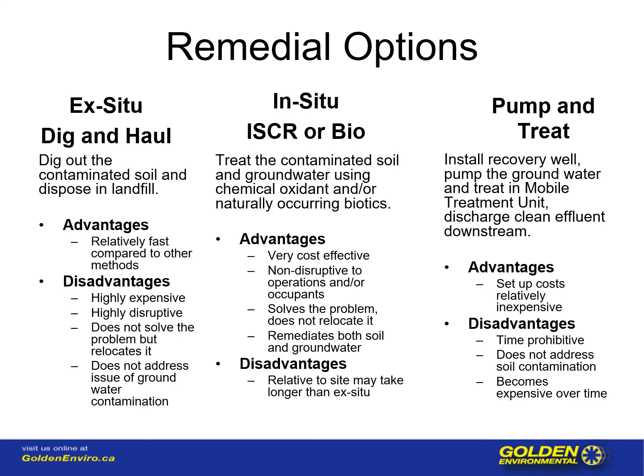Now, if there's groundwater that has been contaminated, it needs to be remediated as well, which adds an additional cost over and above the soil which has been removed. The process of excavating in order to reach your remedial objectives includes digging down to a floor until you have clean soil. As well, you must dig to the walls to make sure that you have clean walls.